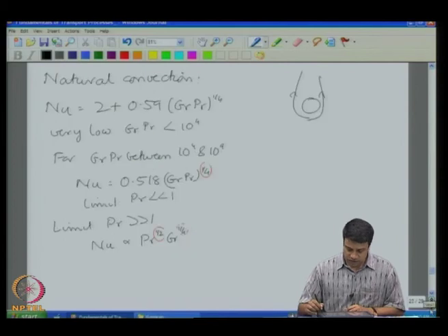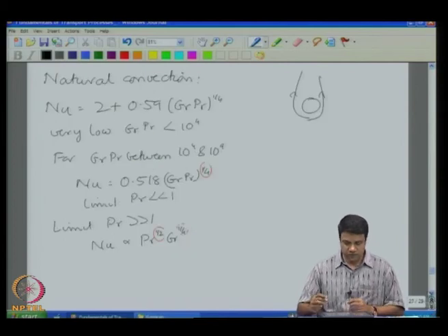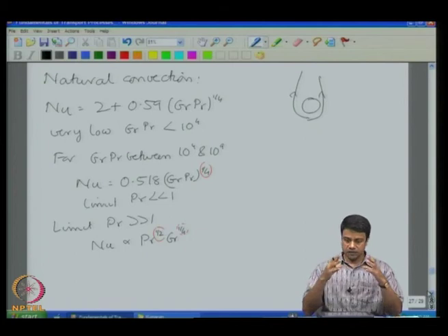So, the remaining course will focus on these different problems, where we actually try to solve for the entire problem around the object. It is difficult to solve for the entire problem, but can we make approximations in regions where we expect either convection or diffusion to be dominant? If the Reynolds number is small, momentum diffusion is large compared to momentum convection. Viscosity is large compared to inertia. You can neglect inertia and solve for the problem by just balancing the viscous forces.